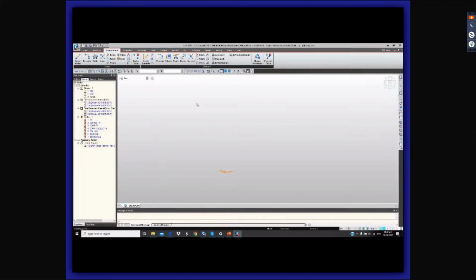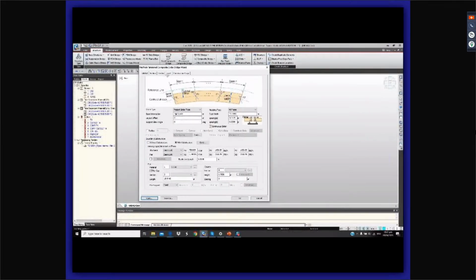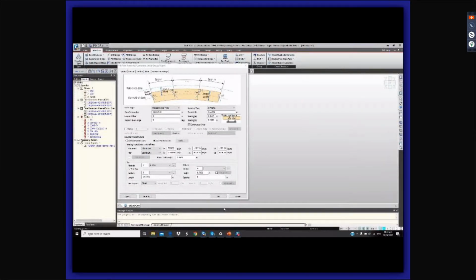For us, the easiest way would be to model it using the structure wizard, the pre-stress composite bridge wizard. The pre-stress or post-tension composite bridge wizard has 5 tabs for layout, section, tendon, load, and then the construction stage. In using your girder bridge wizards, you can open a predefined file and you can also save your created wizard files as a reference for future use.